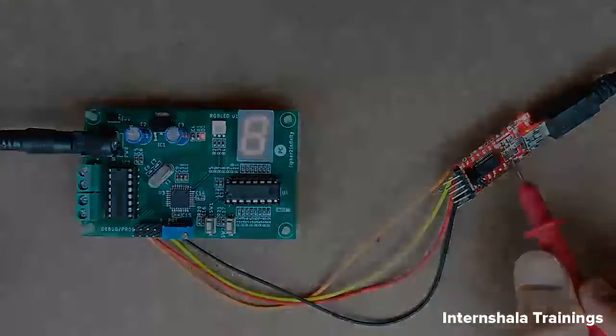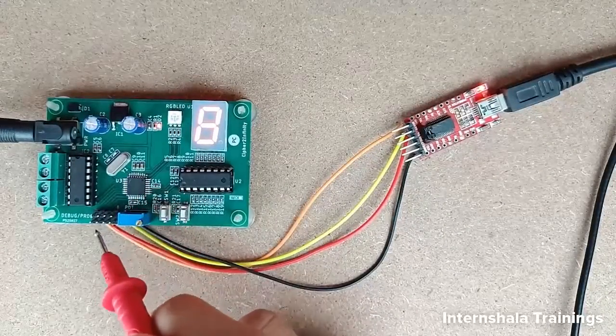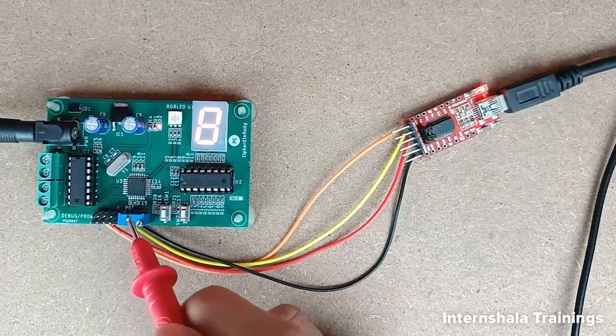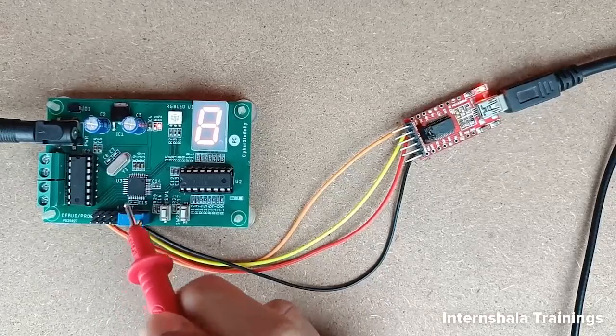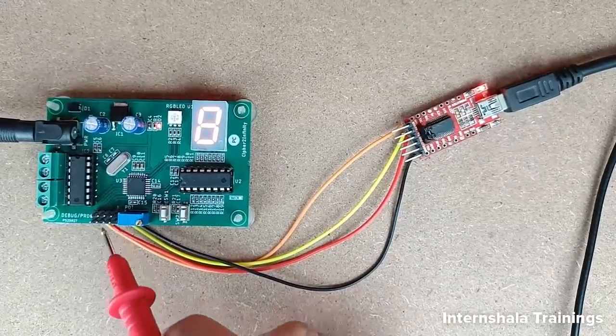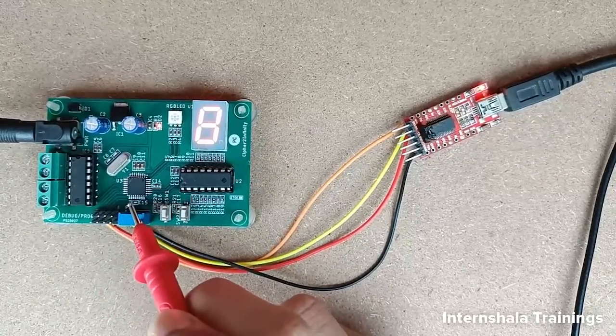Okay. Alright, so that was all about how to send the data from the TX pin of the UART interface to the computer. Now, what we are going to do is monitor the TX pin, and we are going to see how exactly that data or that signal which is sent over the TX pin looks like on the DSO. Okay.